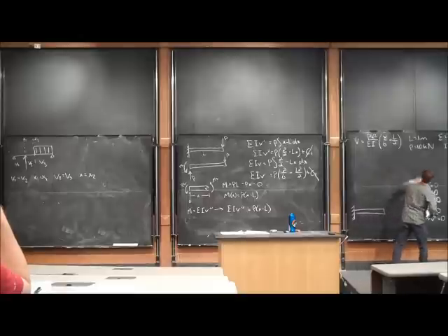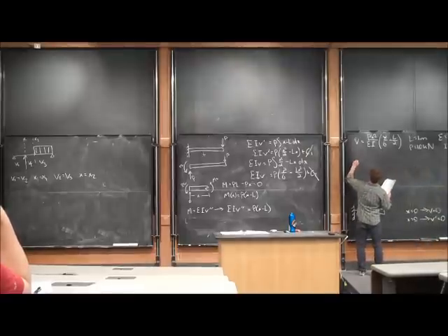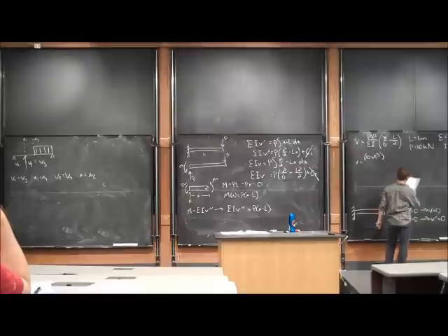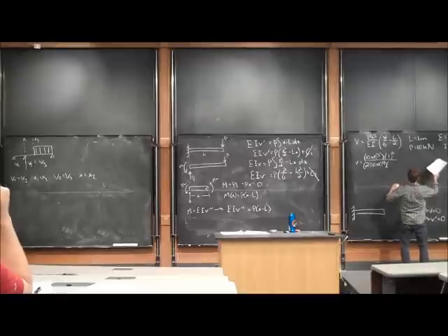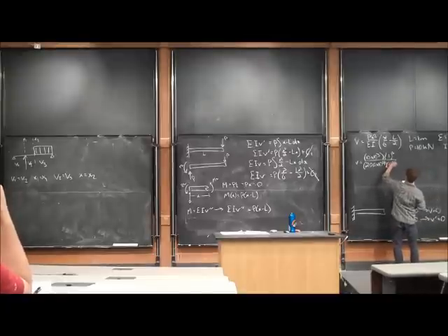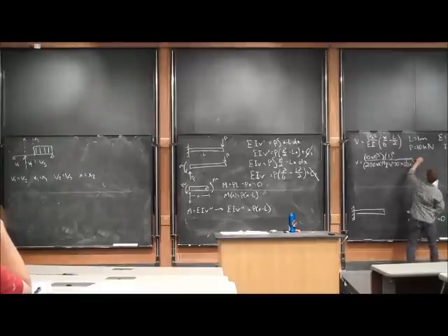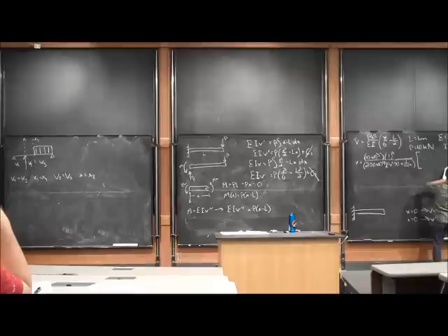We just plug all those numbers directly into that equation, and we would see that V is going to be equal to P, which is 10 times 10 to the third newtons, times X, which is 1 cubed, over E, which is 200 times 10 to the 9, times I, which we said is 800 centimeters to the fourth, so 800 times 1 over 100 to the fourth, multiplied by X over 6.